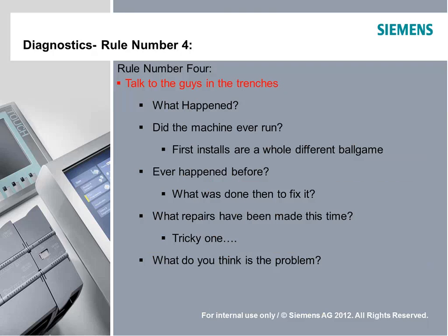So ask them a few questions, and see if it makes sense what they tell you. For example, what happened? Let's just hear it from their mouth. Did the machine ever run? What we mean by that is if this is a startup, it's a whole different diagnostic game than if it's a machine down situation where this was a running machine that faulted out. First installs can have a whole slew of problems, and you never know until all the I/O's been wrung out and everything's been checked whether the machine's going to work or not.